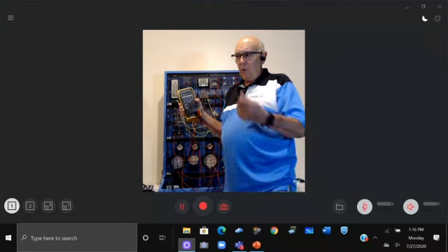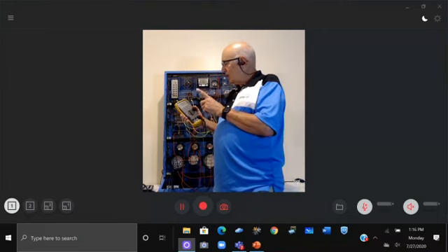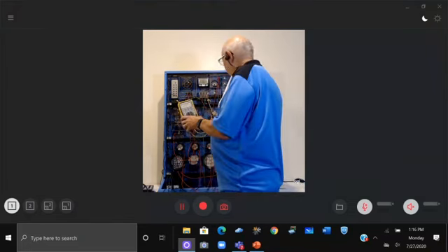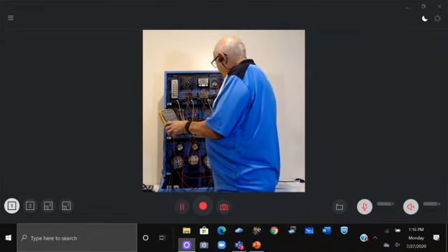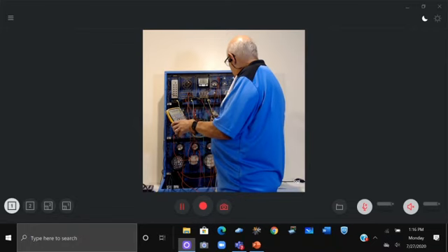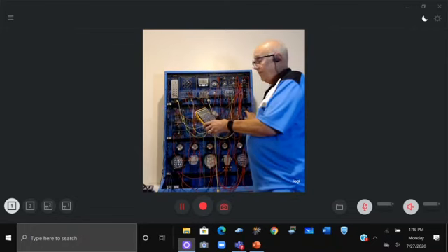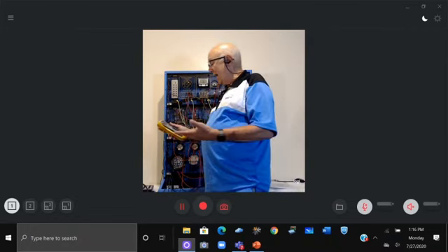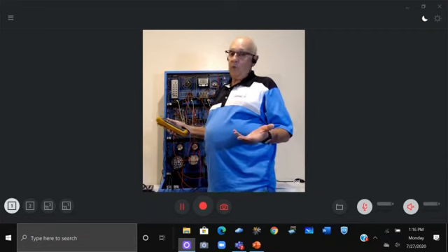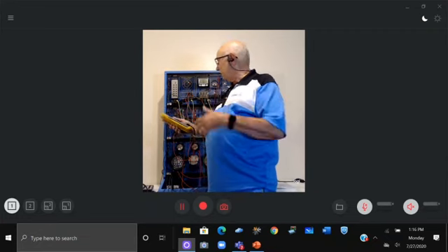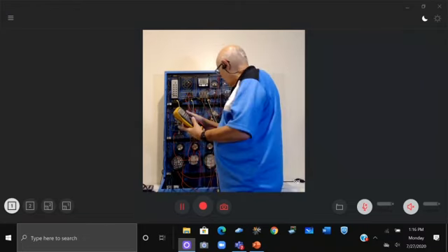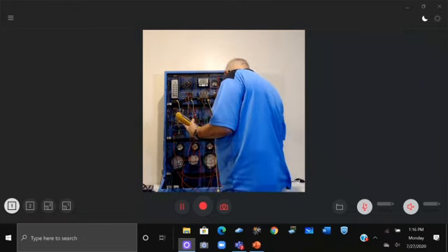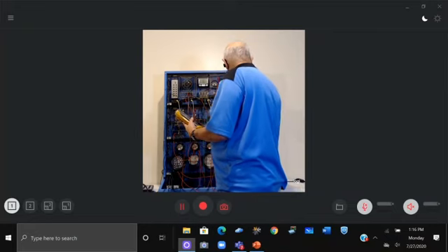Okay? So the first choice I had was I had 60 ohms, didn't I? Okay? I basically have an open circuit now. I disconnected my second resistor. I basically have an open circuit. What I actually have here is 9 mega ohms. 9 million ohms on a car is like an open circuit. Okay? So let me plug them back in.